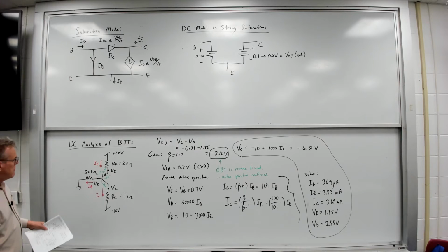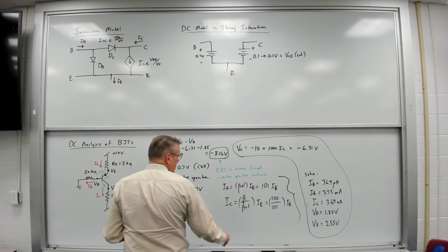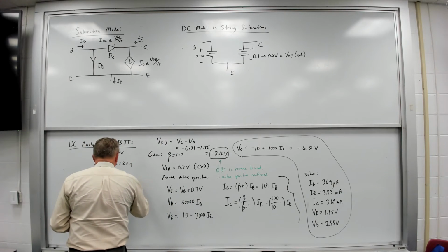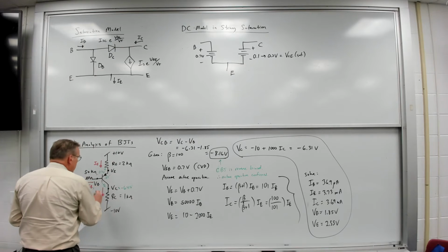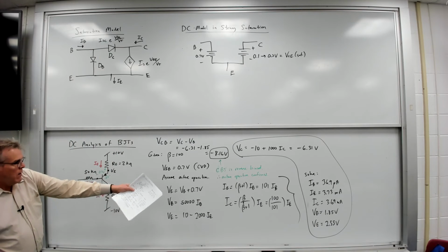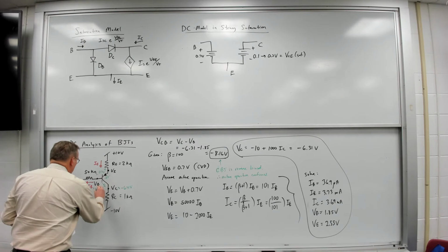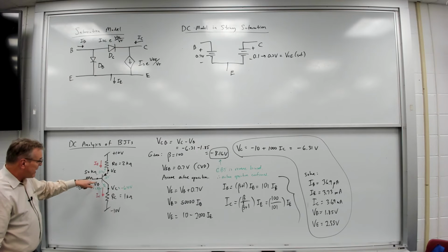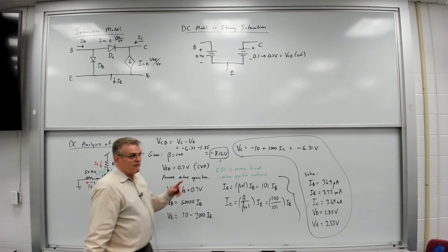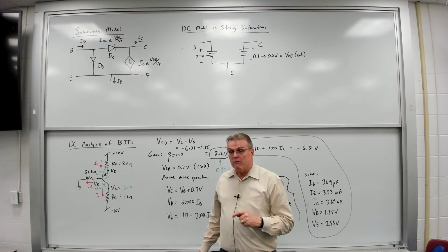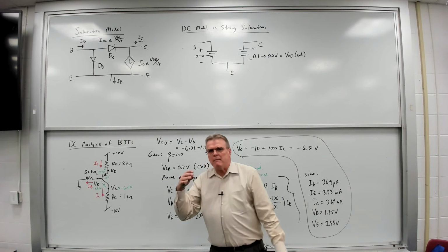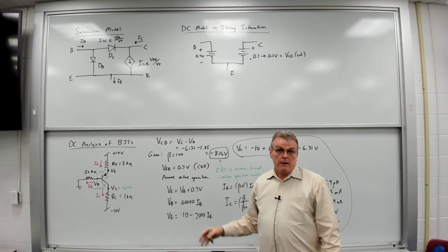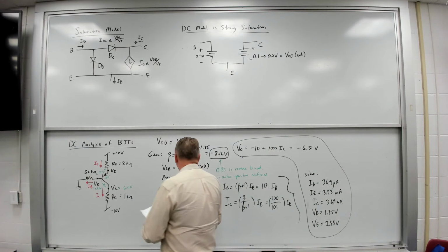And clearly that one's going to be reverse biased, because VC is minus 6.31 volts, and VB is 1.85 volts. So the anode is more negative than the cathode, and that PN junction is reverse biased. It's always a way to think about it: not just doing the numbers, but think about that diode structure. Is it forward or reverse biased?